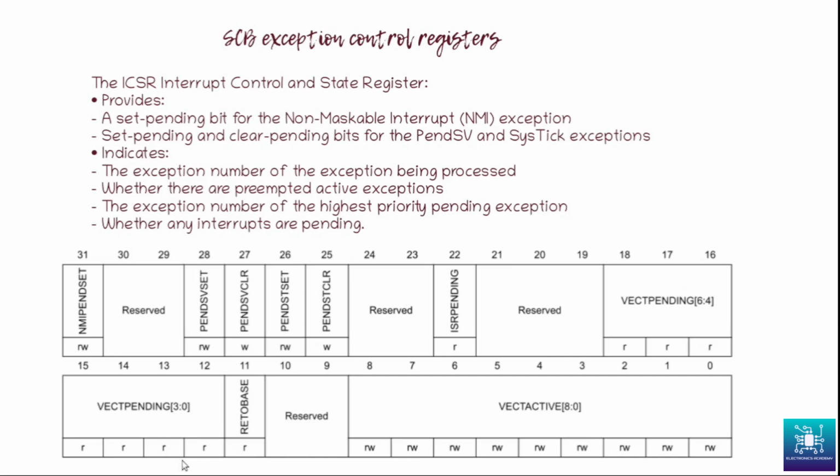So there is a lot of important information that is being conveyed by this register, and we set and clear some interrupts in the system exception range in the vector table. Now, one difference between the layout of this register and the register that we see in the NVIC is that we will have pending bit set and clear fields in the same register in the case of SCB.